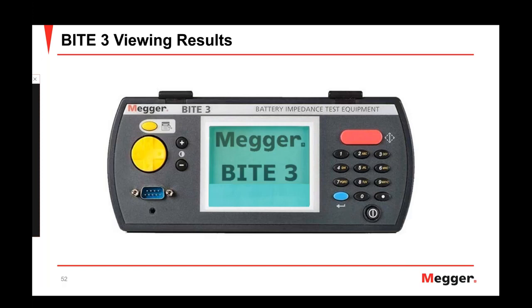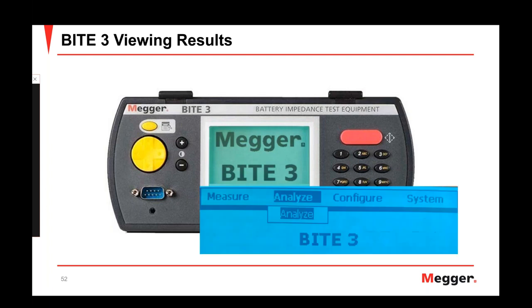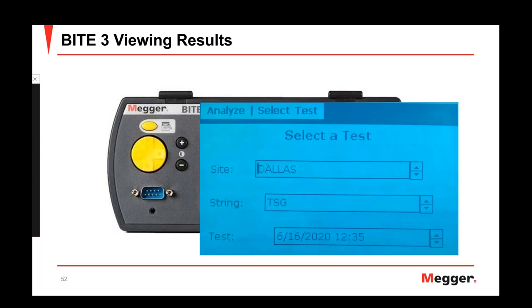So to be able to view the results on the transceiver, go ahead and use the crosspad to select and highlight the Analyze option, and then press the Enter button. That's going to bring up this prompt that we see here, and it's going to ask you to select your site, string, and the date of the test that you want to analyze. So go ahead and find those options, and whenever you're configured with that, go ahead and press the Enter button.